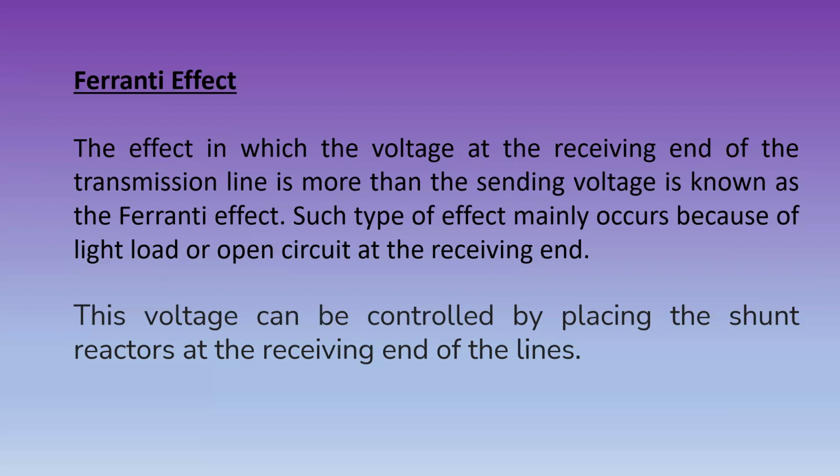Transposition in the transmission line is a technique used to restore some of the electrical voltage drop and current balance of the transmission line system. It is used when the conductors of a three-phase line are not spaced equilaterally. In a three-phase line, all the lines should be spaced equilaterally. If they are not, then the flux linkages and inductance in each phase will not be the same. The flux produced in each phase and the inductance produced will differ, and this difference will make an unbalance in the circuit, with unbalanced current and unbalanced voltage drops.